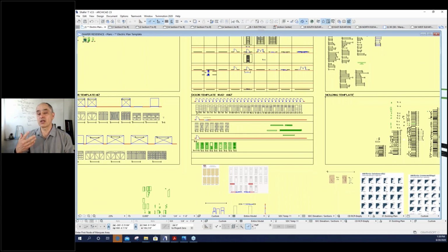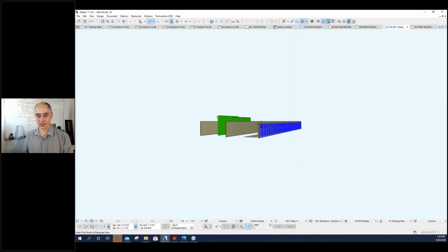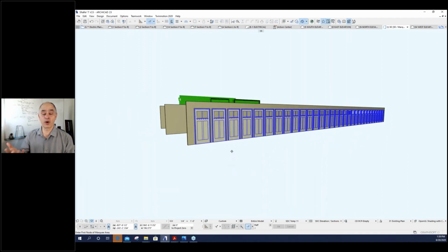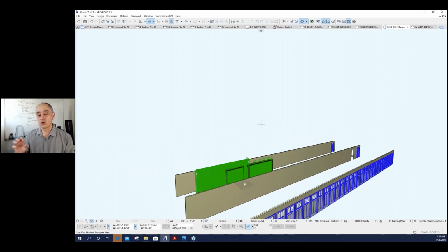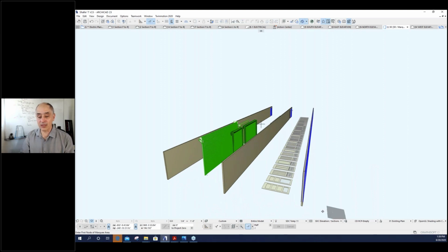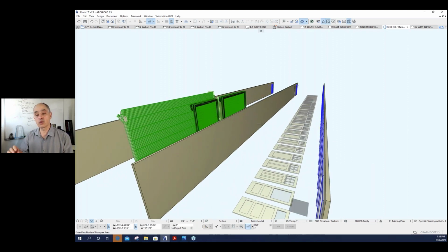So Roger's using the standard door tool where you choose a custom panel, and the custom panels have all been installed into the library. So in order to create a custom door, just as a quick training tip, one way to do that is to draw what would be the door panel lying down on the ground like you see here, and then you save it as a door panel, and then you can choose it from the menu.